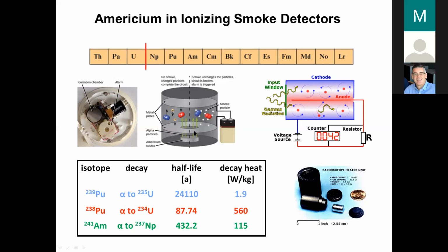So this working principle is identical to a Geiger counter, which you know can be used to detect radiation by the very same principles. So as soon as dust or smoke particles enter the smoke detector and block the beam of alpha particles, which then no longer ionize the gas separating those electrodes, the measured constant current between those electrodes drops. The smoke detector can recognize this and set off the alarm.